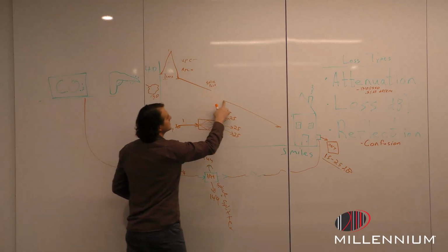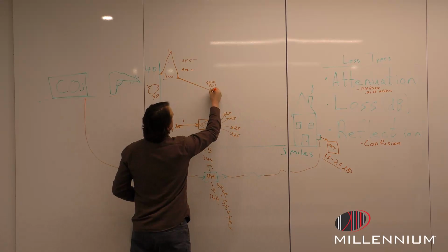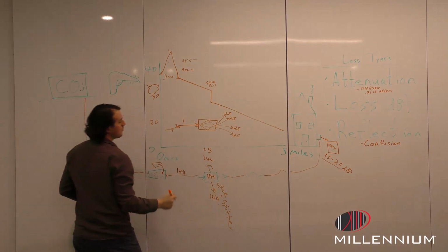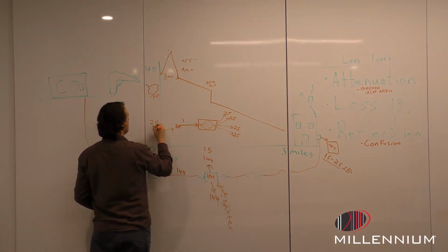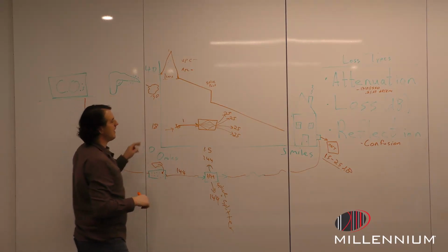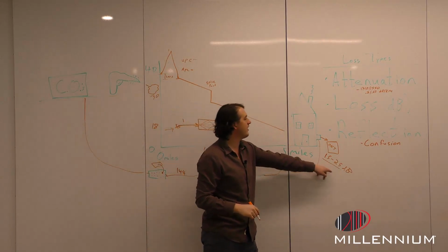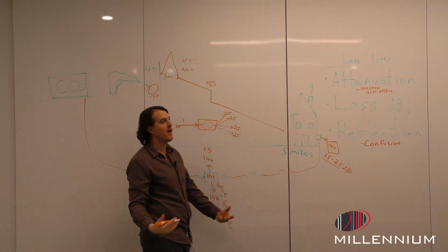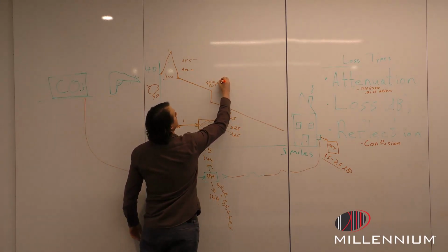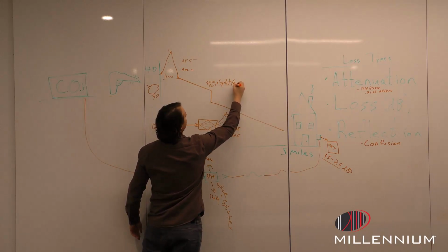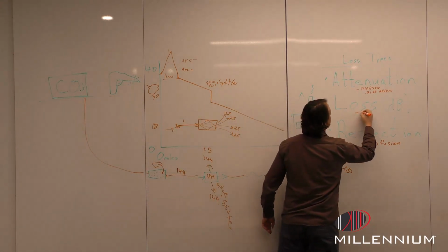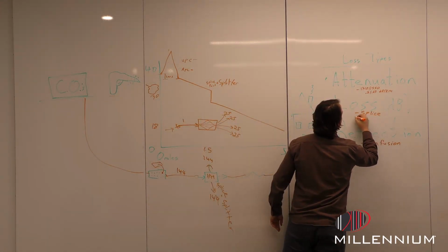So now with that splitter, we lost even more power. Now we might be right at, let's say we dropped a couple extra dBs there. Now we're at 18 decibel, okay? So at this customer's house, we're still within this window. This person's still happy. They still have internet. They can stream their school at home. So we have our splice point and splitter, and that was a huge loss by adding that splitter. But it is the same type of event over here. So a splice and a splitter.